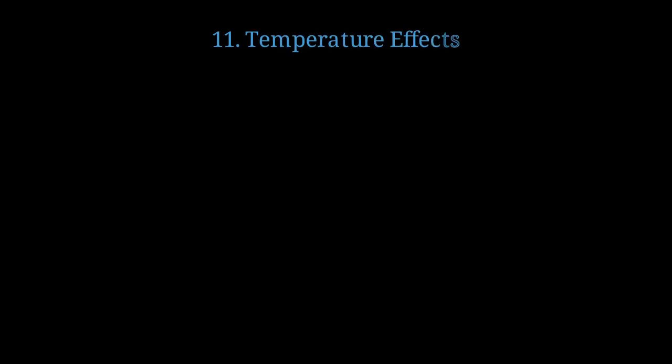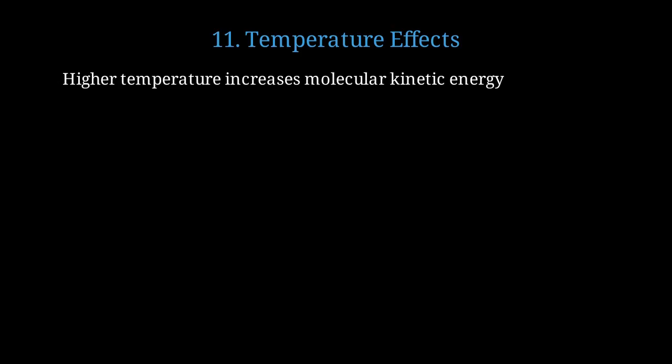Temperature plays a fascinating role in modulating slip length through several mechanisms. As temperature rises, molecules move faster, which affects how they interact with surfaces. Viscosity decreases with temperature following an Arrhenius-type relationship, which indirectly affects slip.